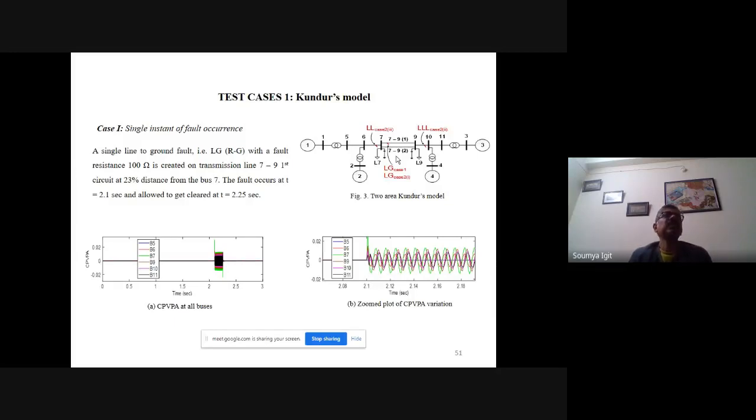But the question is that if there is a simultaneous fault, one fault is not cleared and another fault gets in. So for there, suppose the initiation of the traveling wave and the formation of the Bewley lattice structures, the first arrival time of the traveling wave, it is very difficult if you are concentrating on the high frequency component.